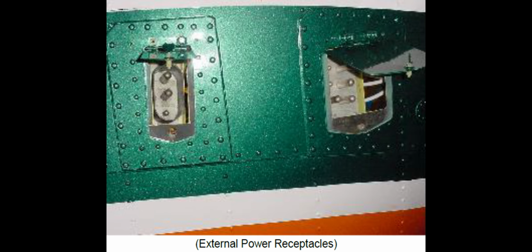AC external power control relay. The AC external power control relay is located on the right attic compartment shelf. The relay is a double pole, double throw contactor relay. When AC external power is applied to the helicopter and the generators are not supplying power, the normally closed contacts complete the path of DC control voltage from the external power monitor panel to the external power primary and monitor bus relays. With external power primary and monitored bus relays energized, AC external power is applied to the helicopter buses for distribution.